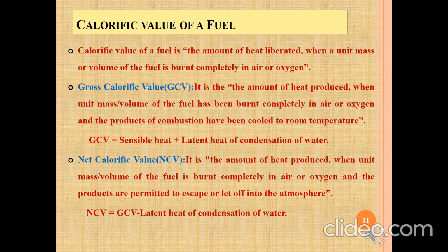Next is net calorific value, that is NCV or low calorific value. It is nothing but the amount of heat produced or liberated when a unit mass or volume of the fuel is burned completely in air or oxygen and the products are allowed to escape into the atmosphere. So here in the net calorific value, the products are not cooled to room temperature. They are generally allowed to escape into the atmosphere. So NCV is nothing but GCV minus latent heat of condensation of water. So always NCV is lesser compared to GCV, since the products are not cooled, they are generally let off into the atmosphere.